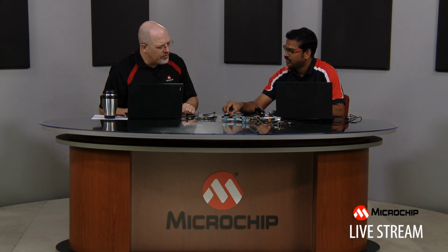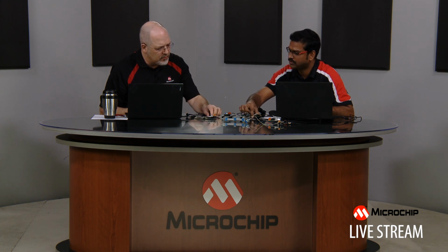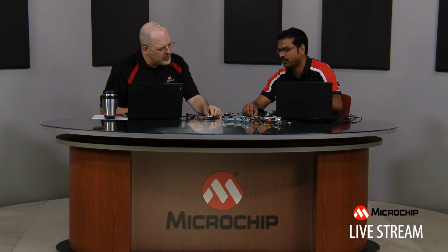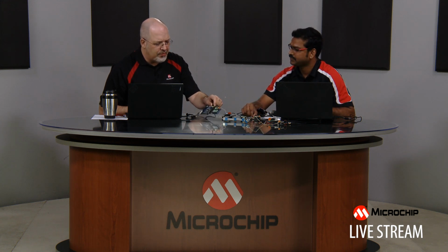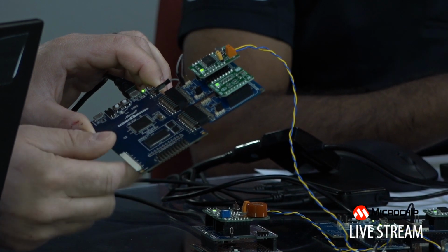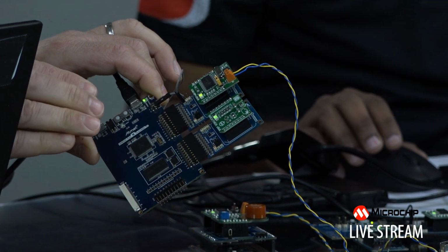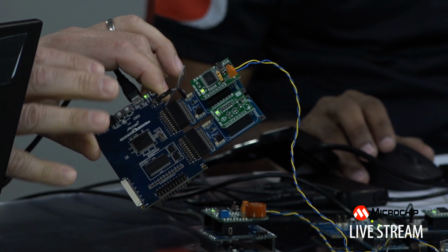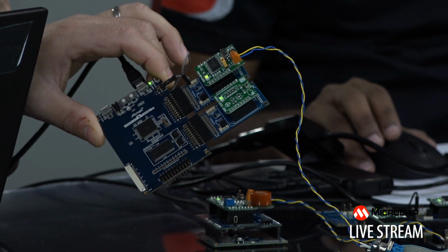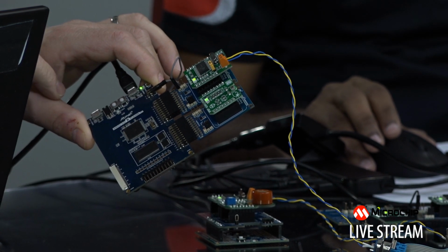Okay, and what about the Pros? How do you connect them? They have standard connectivity, which uses the mikroBUS. We have provided this mikroBUS interface. The extension boards can be connected via this. Just to point out here that if you look at the Pro boards, you'll see they have these extension headers on them. The goal with those is to connect into these Xplained Pro extension boards. And we sell a bunch of those: there's some for I/O, some for LCD, an analog interface, and so on.